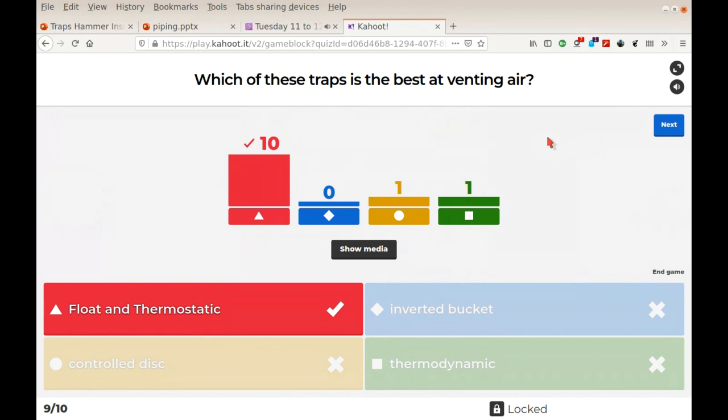We want to get the air out of the steam, basically due to Dalton's law of partial pressure. If we have air in the system, it's occupying a certain amount of space. It's part of the pressure, and the temperature will be less because the air is occupying part of that space. So we've got to get rid of the air from the steam system.